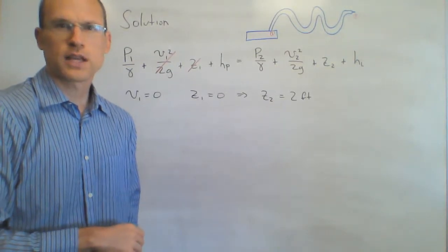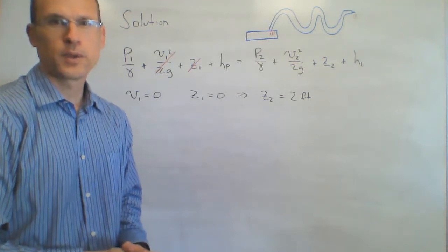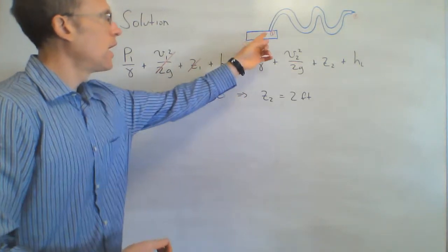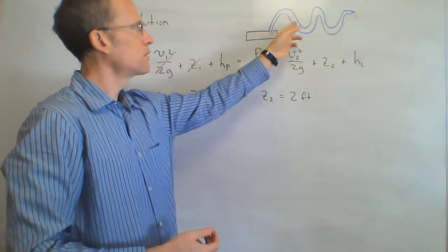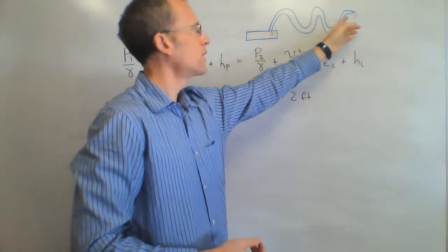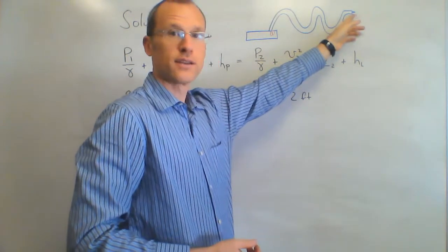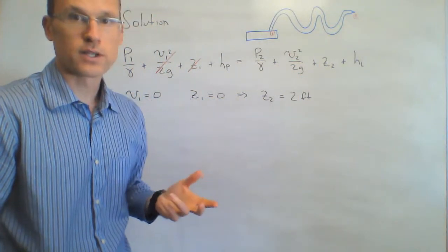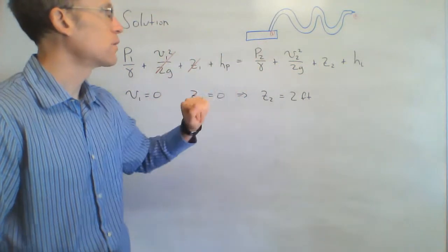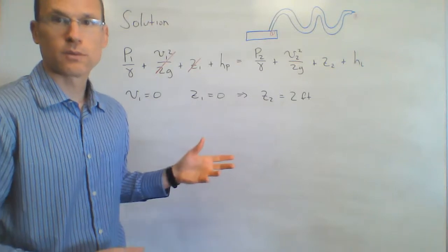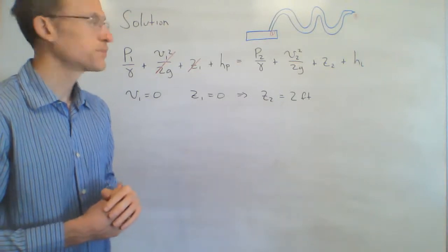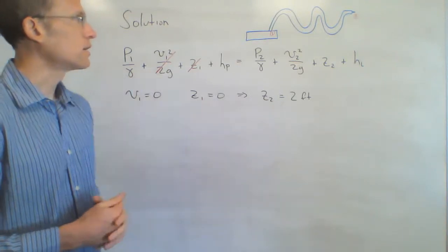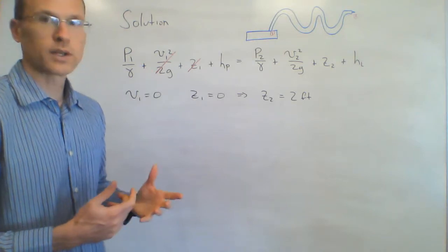So to solve this, helps to have a little diagram to see exactly what's going on. Shove my gas tank down here. I have this 1/4 inch tubing, 5 smooth bends, then it contracts into a 1/32 inch jet, then it goes up into the carburetor. So that's kind of what's going on. Begin with Bernoulli's equation, full energy equation. Then want to make this guy easier. So what can we get rid of?